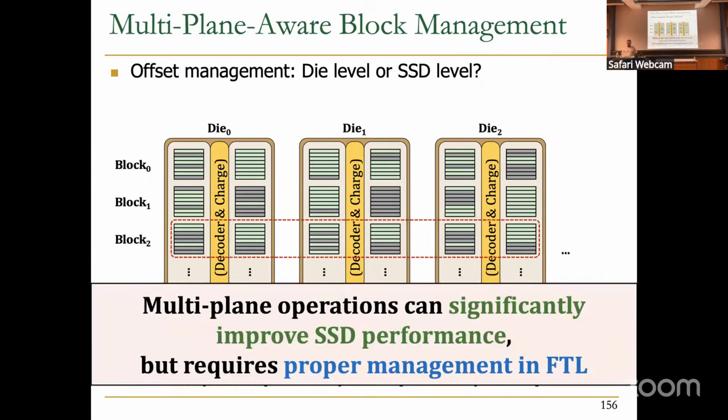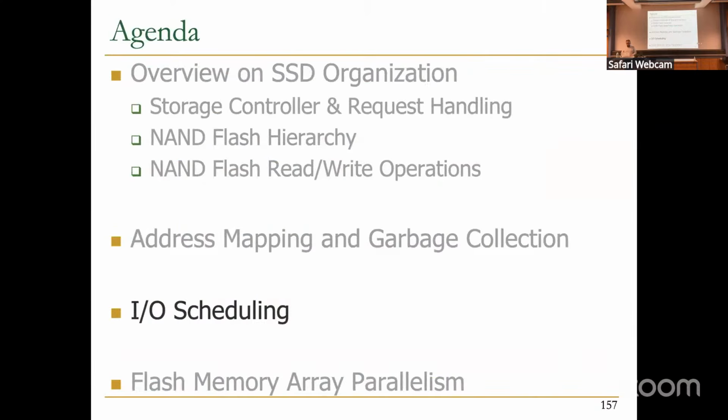So multiplane operations can significantly improve SSD performance, but require proper management in the FTL. The FTL should be aware of that when doing garbage collection and block management, such that we can benefit from multiplane operations. Make sense? Very good. Okay, I'm happy.